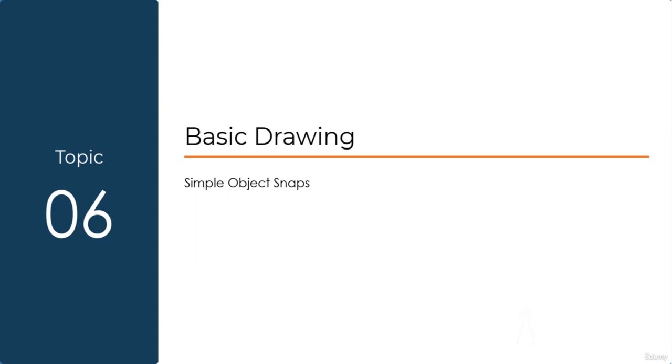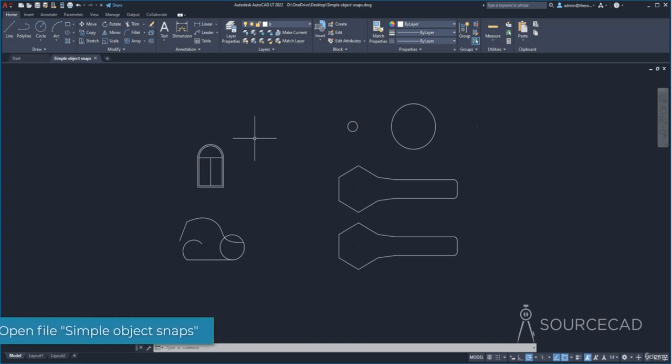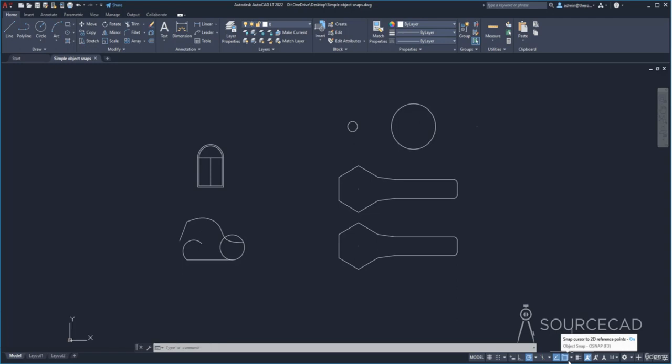So now let's talk about Object Snap. And using Object Snap, you can make drawings precisely. Now the Object Snap toggle is right here on the status bar. Its function key shortcut is F3, as you can see here on the tooltip. So you can just toggle it on or off using the F3 function key as well.